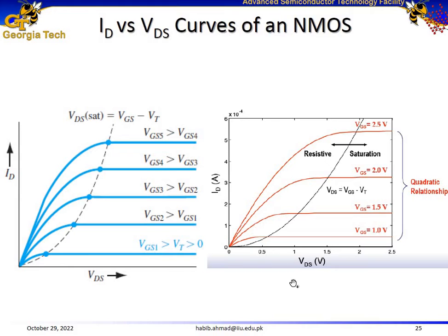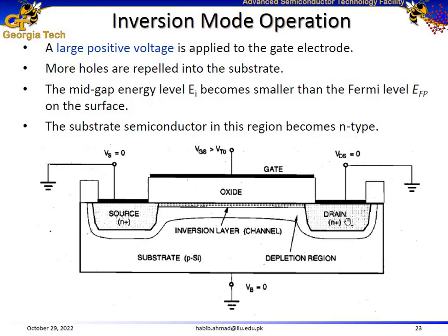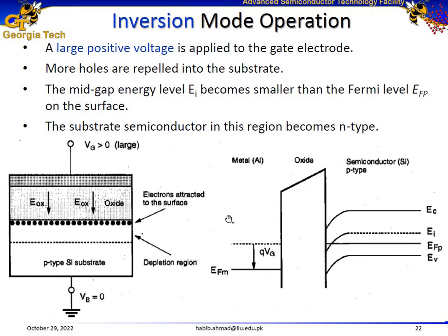As you can see, as we increase VDS, ID is also increasing in the linear region, and then there is a saturation region as well. So if you just consider an NMOS, if you increase VG beyond the threshold point, it's going to increase the current across the channel as well, right? So you have a voltage and you have current.